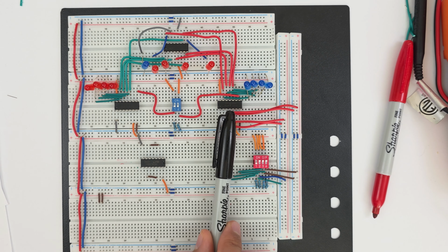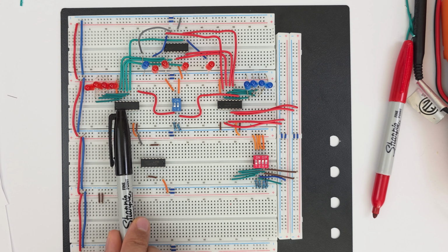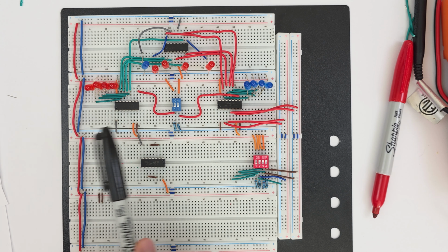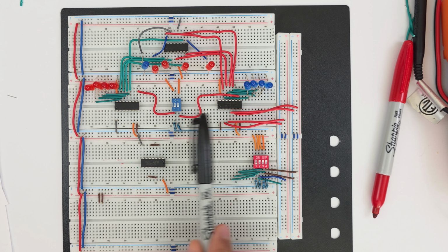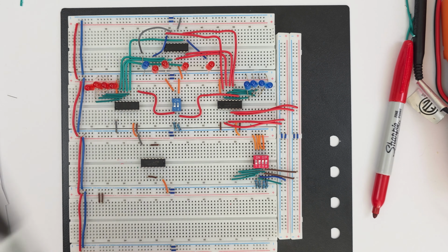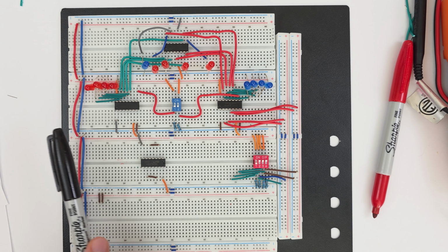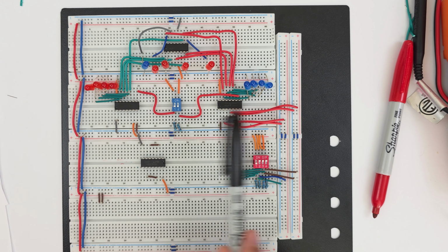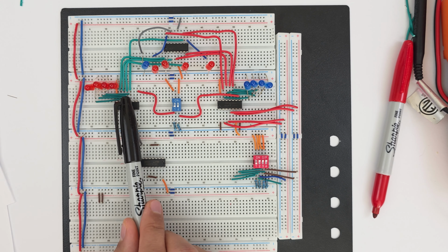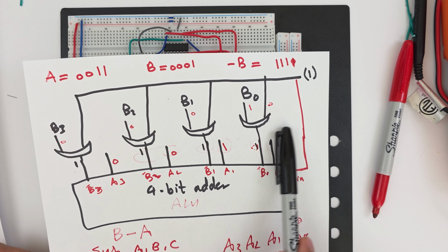If you look at R1, it is connected to the bus and from the bus to the ALU directly. But for R2, there were 4 wires here that I removed. These wires were connecting R2 to the bus and taking the register output to the ALU. Now this register is not connected to anything, not to the bus or the switches. Why am I doing this? Because I want this register to take the values from the output of the XOR gates.